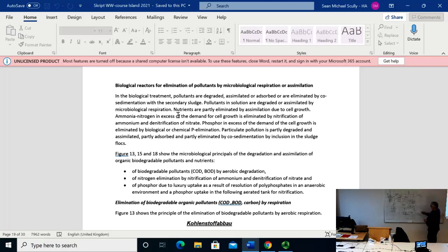and out of this gram which we have here, if we digest those and make it to biogas, of course they release another 0.5 grams that come back here, no? So this comes back, 0.5 grams of N per day from the sludge treatment, if we have anaerobic sludge treatment, because half of this biomass we're going to degrade.